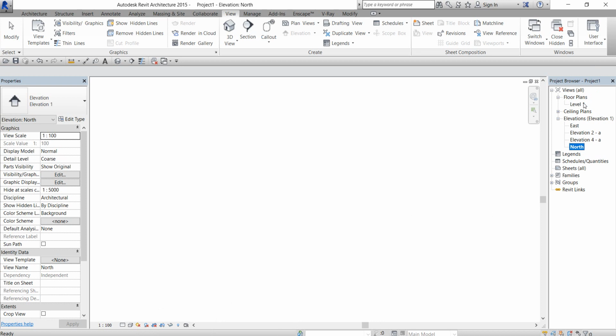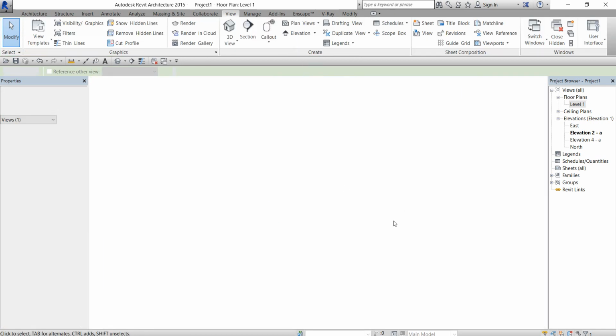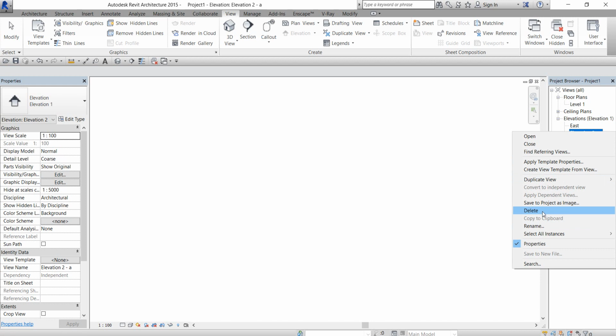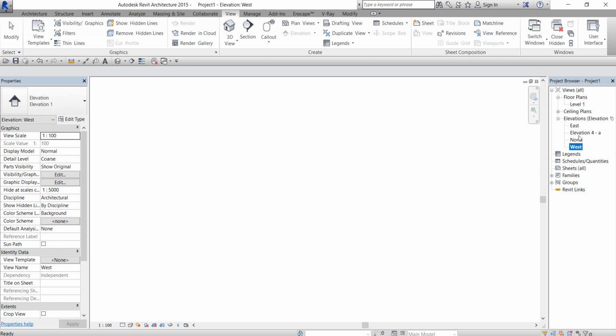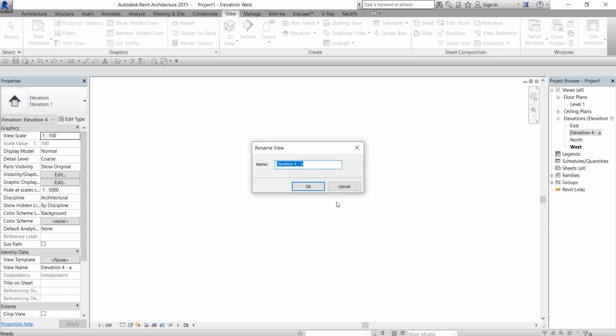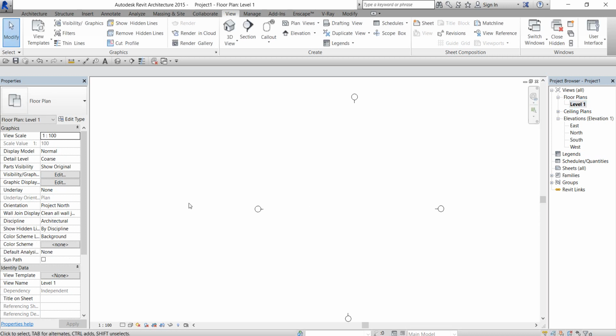now go back to the floor plan, select this east one, go to elevation and call it, that is west, left hand side, call it west. Say okay. Since you have gotten them, the last one, you don't need to go there, just rename it from here because that's the south. You type south and say okay. So you have the whole 4 cardinals in place.